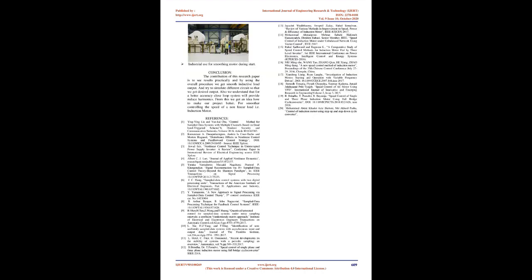PWM generator: outputs a pulse to the electronic switch of a 1-quadrant DC to DC converter. The duty cycle, input D, determines the percentage of the pulse period that the output, P, is on. Here we set a switching frequency of 100 Hz. Simulation results of the MATLAB model.